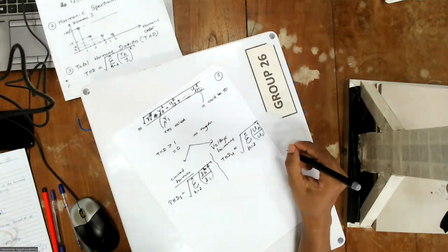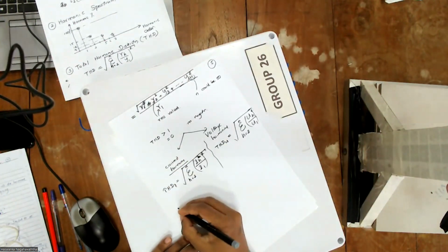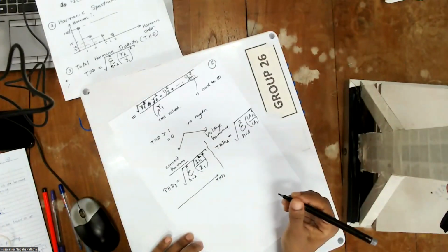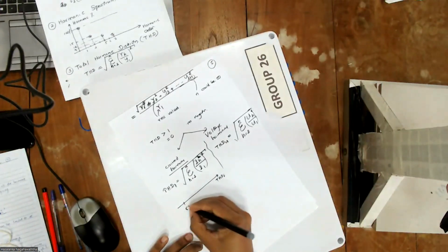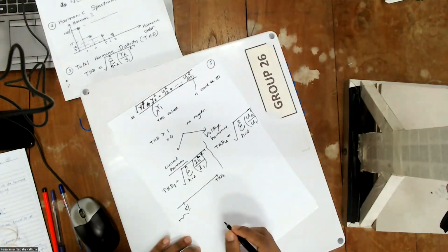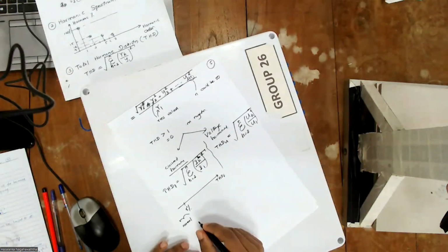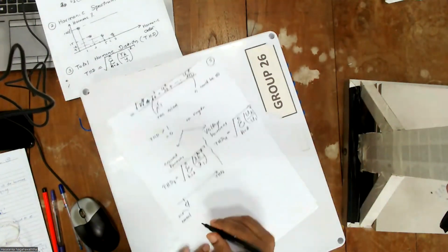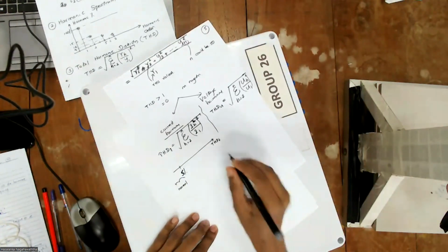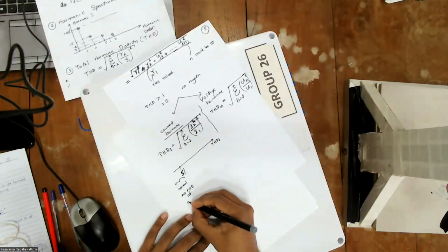So here, if you are measuring current harmonic, this is the THDI, and if it is below 5%, it is normal and there is no risk of malfunctioning.